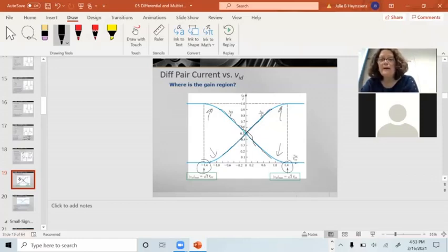Let's say you've got a 50 millivolt signal coming in, and you're trying to run this circuit off of a 5-volt power supply reference to ground. Your 50 millivolts is really close to ground. You're going to be in one of these gain regions where you're not very linear. You're not going to have a lot of accuracy there. And the only way to fix that is either to add a DC offset to the 50 millivolts, which is going to be sloppy, or put a negative power supply in.